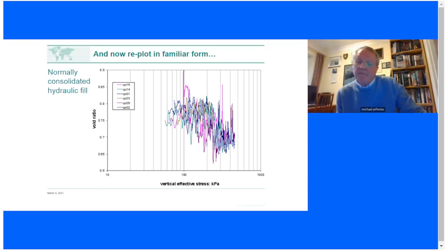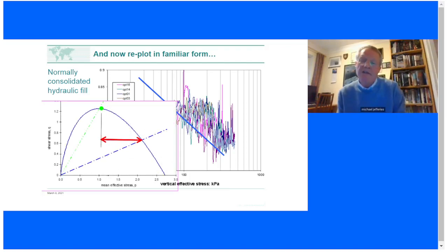Is it there? Or here? Or here? Or here even? In fact, what you see, you've got a complete zone of it. So let me now bring into the picture our yield surface, our Cam clay yield surface. Now, bear in mind, my berms are more or less low aspect ratio structures. I'm actually testing here in the middle of the berm. So this really is 1D consolidation.